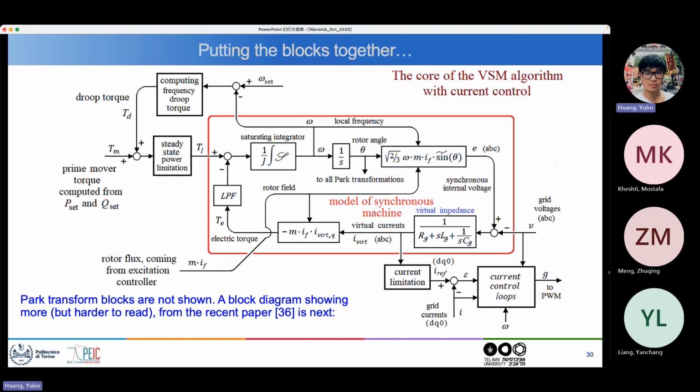The omega is changing at a slow rate. So if you have this round trip delay, and you can align the signals, as Florian explained, using timestamps, then you can actually help to diminish the inter-area oscillation.